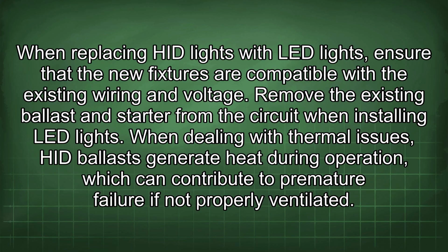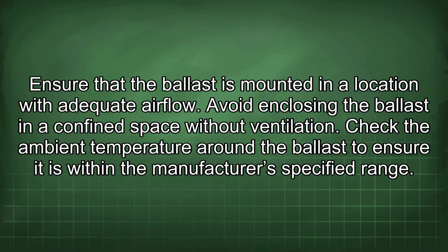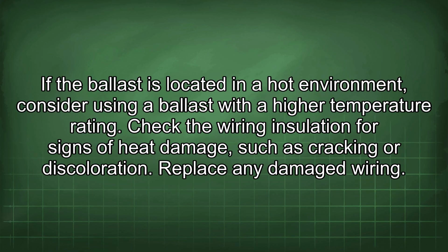When dealing with thermal issues, HID ballasts generate heat during operation, which can contribute to premature failure if not properly ventilated. Ensure that the ballast is mounted in a location with adequate airflow. Avoid enclosing the ballast in a confined space without ventilation. Check the ambient temperature around the ballast to ensure it is within the manufacturer's specified range. If the ballast is located in a hot environment, consider using a ballast with a higher temperature rating.